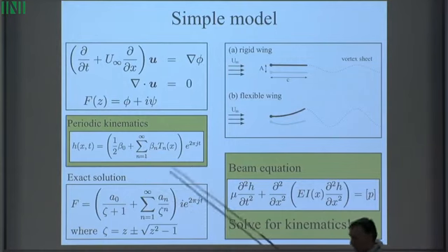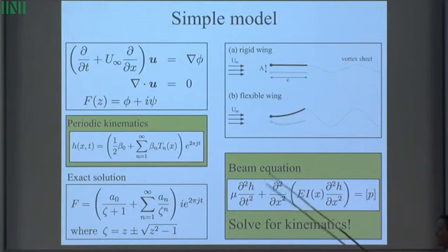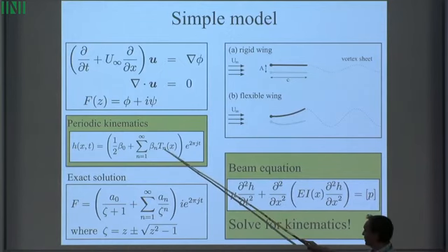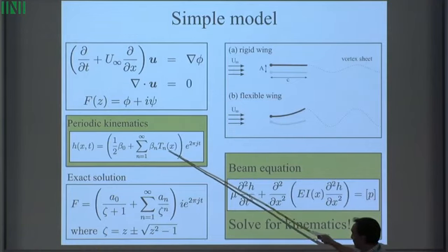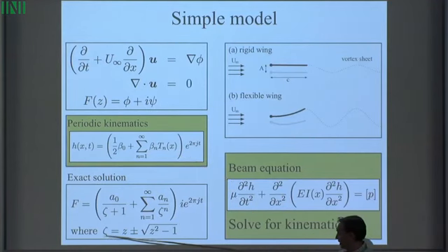Okay, well, a polynomial series of some sort. I choose a Chebyshev series, and the reason is that it pops straight out of the Joukowsky transform that I used. So in the wing space, a Chebyshev series is going to be a Fourier series on the circle. Okay, and that's the big advantage to using Chebyshev here.